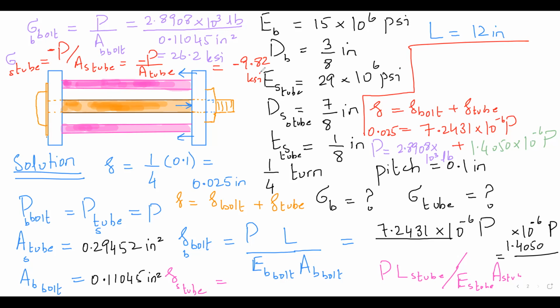So the actual answer for the radius of the steel, right, is going to be alpha minus 1. Is that how we found the area of the tube? The area of the steel tube, we got it as pi r2 square minus r1 square. So outer radius is known. Inner radius you have to find. Inner radius is the outer radius minus the thickness.